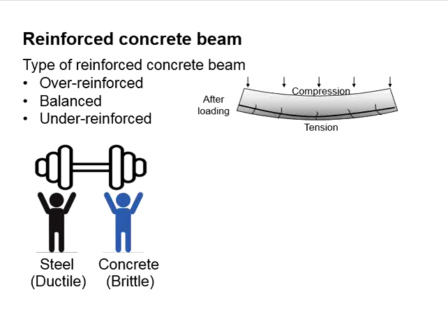Now, which do you prefer? Do you prefer the steel to fail first, or you prefer the concrete to fail first? In reinforced concrete design, we don't like brittle failure, as it does not give us warning prior to failure. In the case of overloading, we do not have sufficient time to respond to the failure. Therefore, for survival purposes, we want the members to fail in ductile.